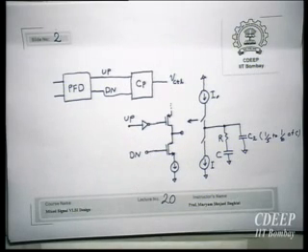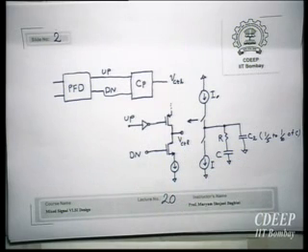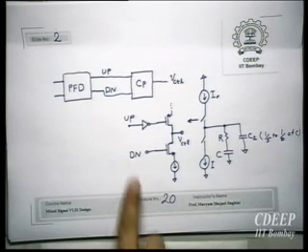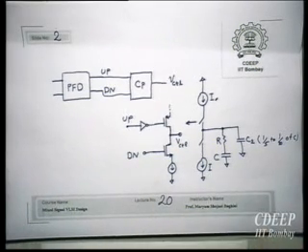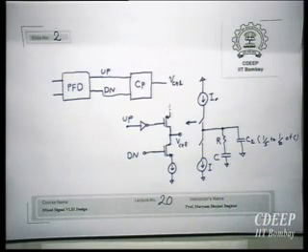But now the problem is I'm creating a delay from down to up. Therefore, these two won't have the same phase performance. So there is a delay. And because of this delay, effectively I'm creating some offset in the output voltage of this circuit, and that also appears as ripple.